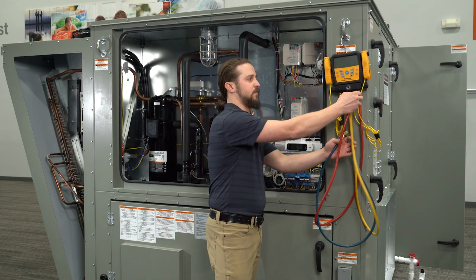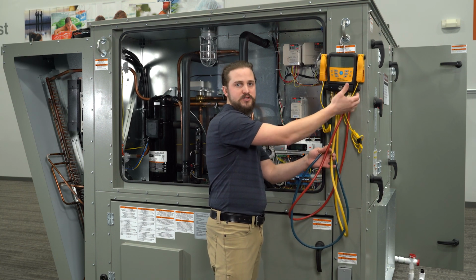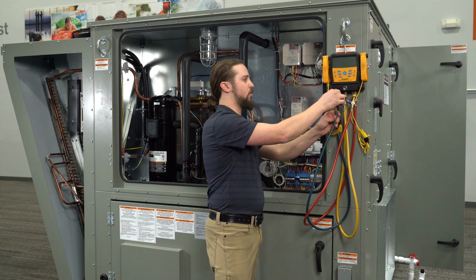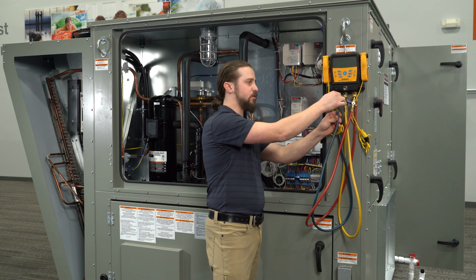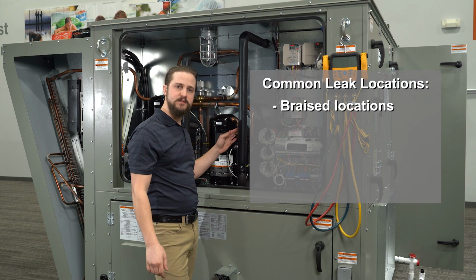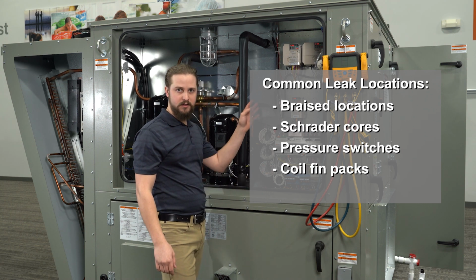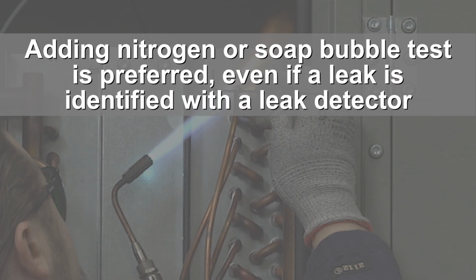With using a refrigerant leak detector, it's typically best if the circuit is not flat or if you still have refrigerant in the circuit. You're going to want to just do a pass around the whole unit, looking at locations such as brazes, Schrader cores, pressure switches, coil fin packs, and coil U-bends. If your refrigerant leak detector does alert on any of those locations, we would still prefer if you follow that up by charging with nitrogen or simply performing a soap bubble test.